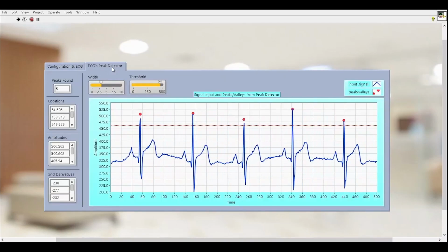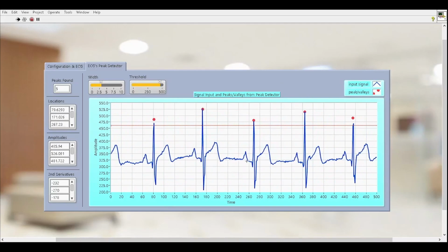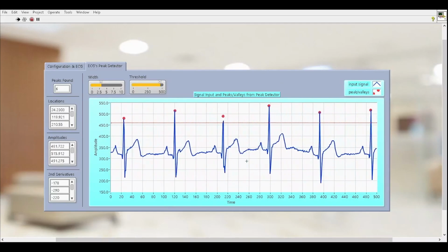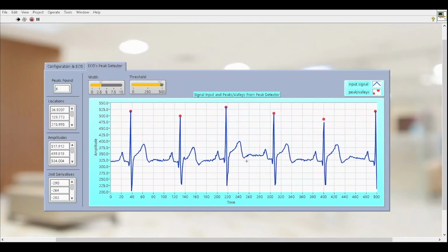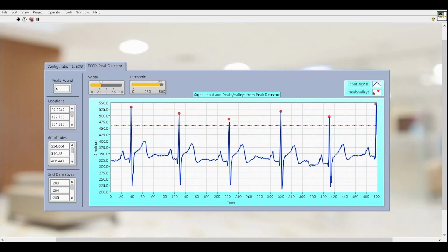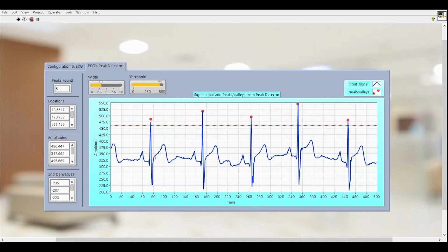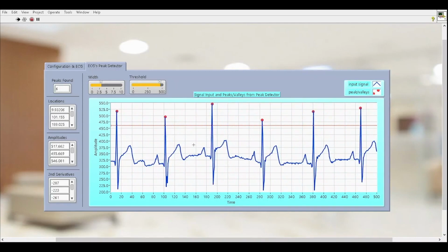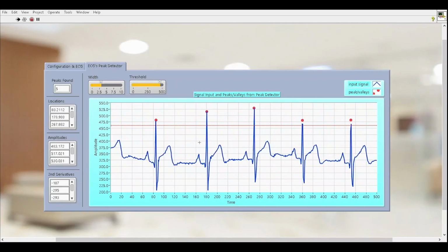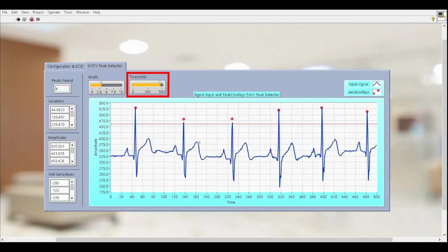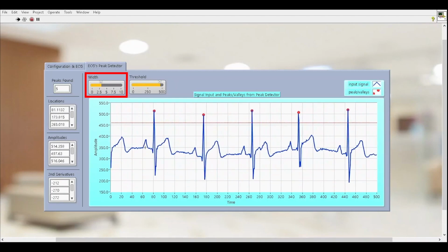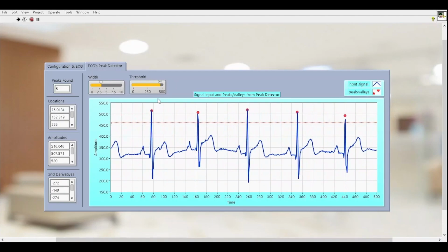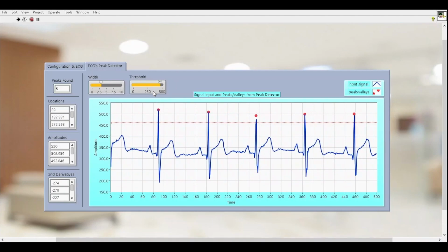This is the ECG beat editor. We have a graph showing the same ECG wave as the one in our first tab. This tab is for finding the QRS beat of the wave, and one peak is equivalent to one beat. After doing some research and measurement, we have calculated that the threshold should be 450 and the width between beats should be 3. By counting beats from the ECG wave, we will know the patient's heart rate.